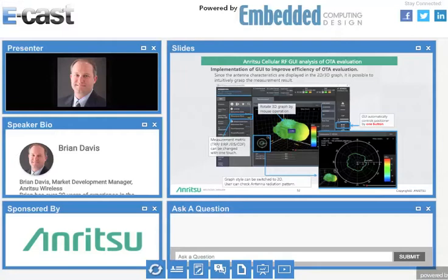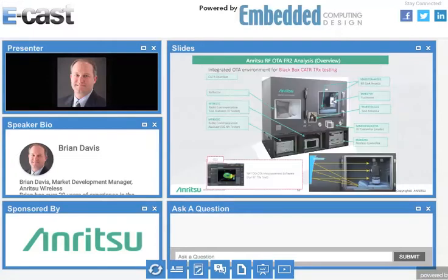We can rotate, position the view. So you can look at peak beam search, for the FR2 side stuff, looking at radiated power, that sort of thing. This is our CATR chamber. CATR has been a popular chamber architecture for 3GPP and a lot of the OTA testing out there. But it uses a reflector. It's a compact antenna test range to shrink down the size that you need.